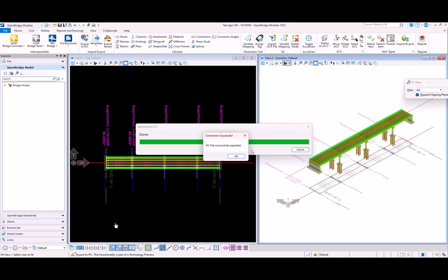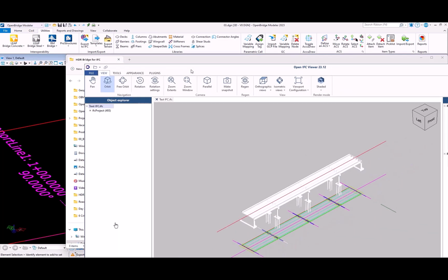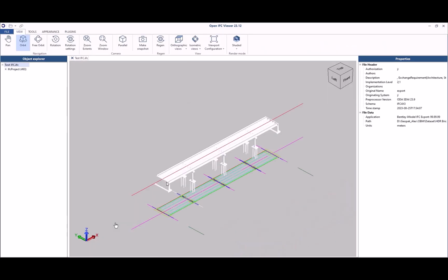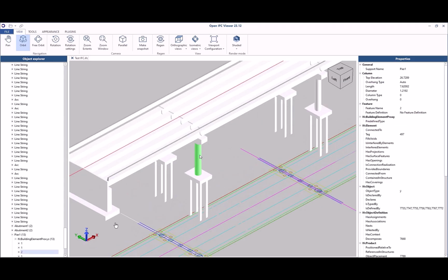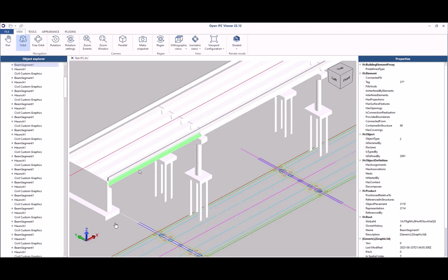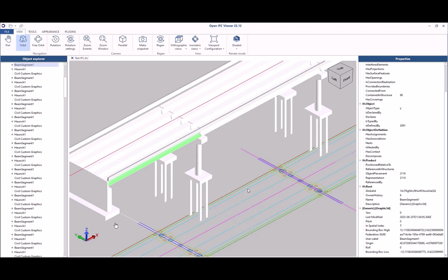So this file will contain all that information, and we can share it externally to non-application users. They will need a viewer that is free in the market. There are different ones of them, BIM Vision or OpenIFC. So that's what I'm using right now. So I just load that IFC and I see all the properties. These files follow a specific structure, a specific wording that it needs to use to classify each element that is being studied by different DOTs. So it's a work in progress.